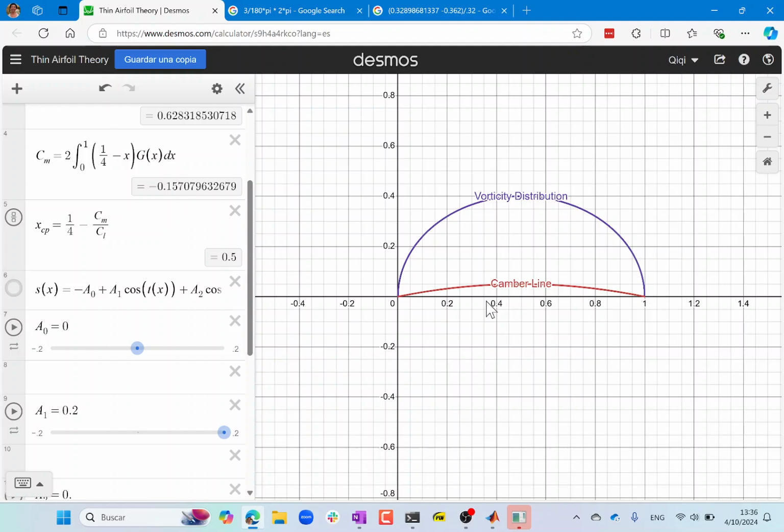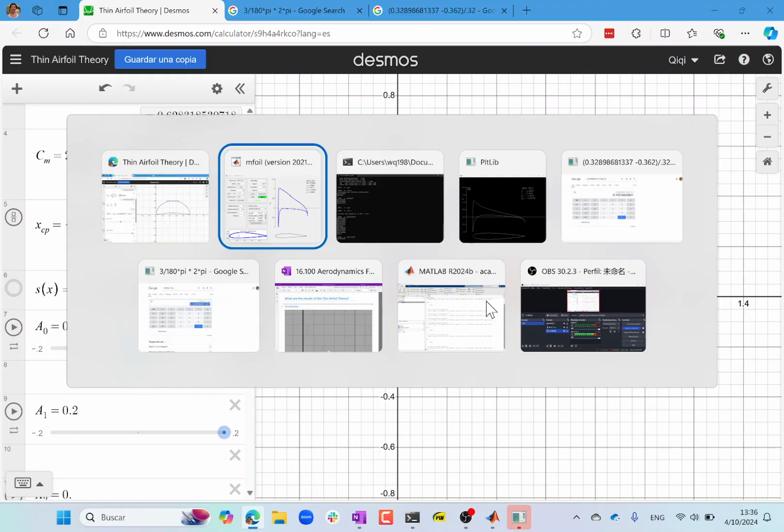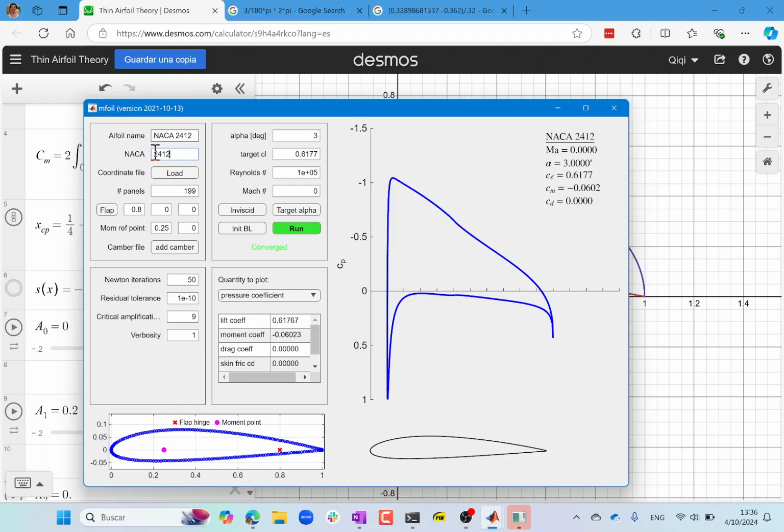Right in the middle, right? How many tenths is right in the middle? 5, right? So to get something similar to what we looked at in class, which number would you change, and what would you change it to? Second number, you change the second number to 5, right? Instead of 2412, you do 2512.